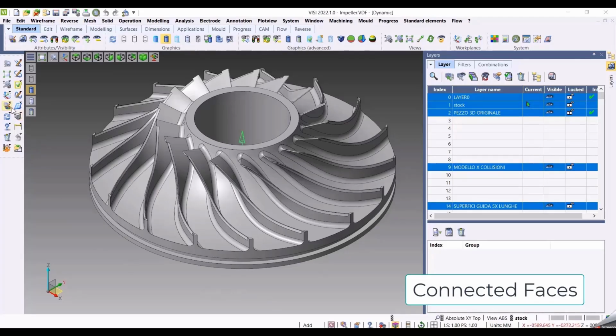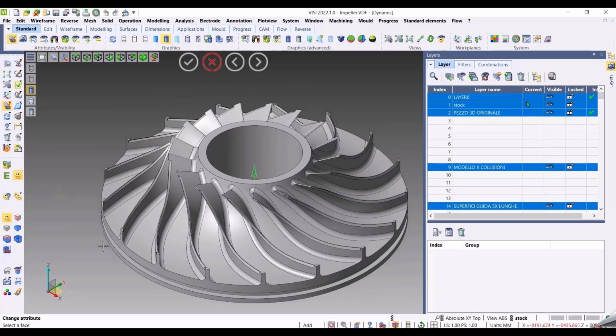We'll just go over these enhancements real quick here. I'm using a command that involves the faces environment. I'm going to use block control as far as my selection, but before I do, you can see how when I'm drawing a window, it's selecting everything within that window. So here's block control. Let's say I pick this face right here. If I use this new option called select connecting faces, drawing a window, it only picks the faces that that selected initial face chose. So it's not picking anything else.